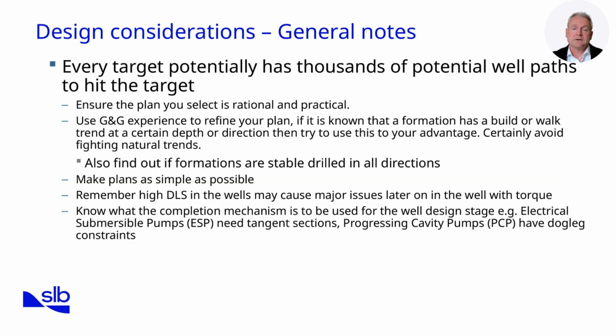When planning a well, thousands of possible trajectories may exist for a given target. The challenge is to refine choices into practical and rational options. Key considerations include avoiding high dogleg severity, accommodating casing and completion requirements, and ensuring hole stability.